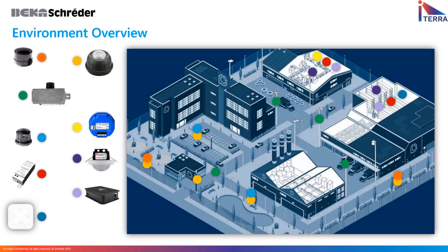The network is created for that complete environment, and we can have several areas autonomously running by themselves with these controllers. All of these run within that network environment, and because they're Bluetooth, as long as that Bluetooth network is on in that area, these nodes will run the luminaires accordingly.